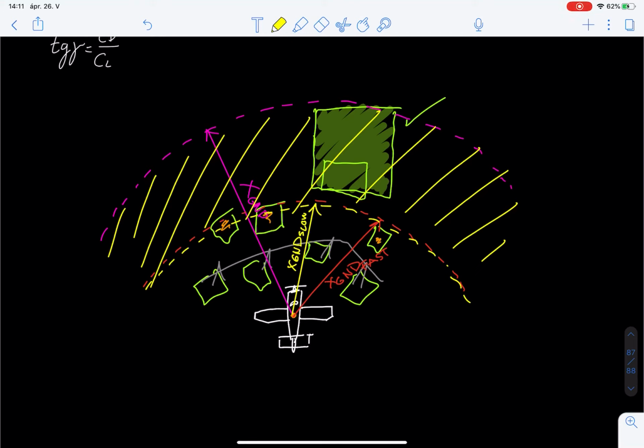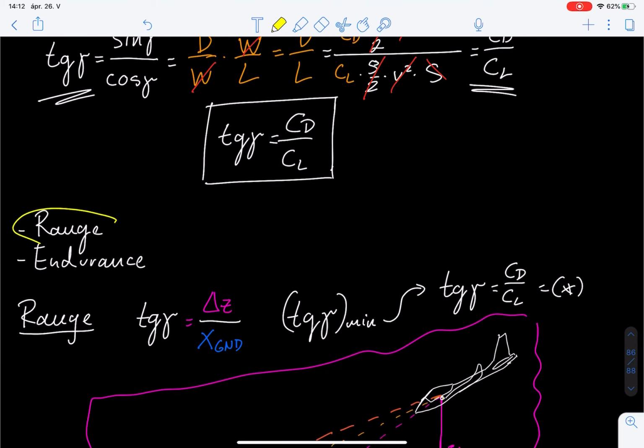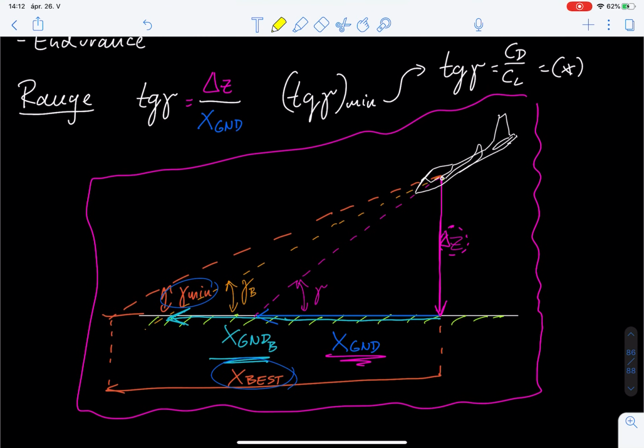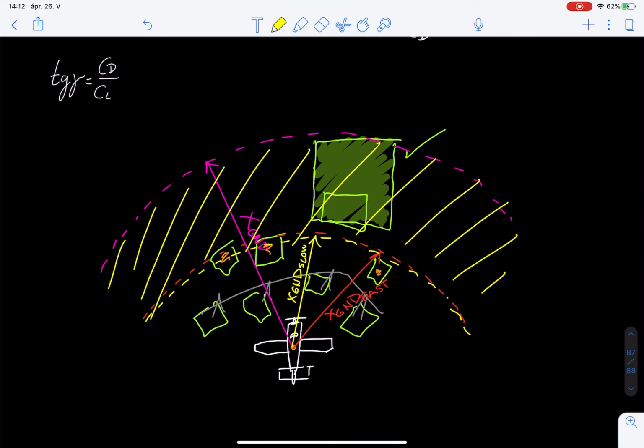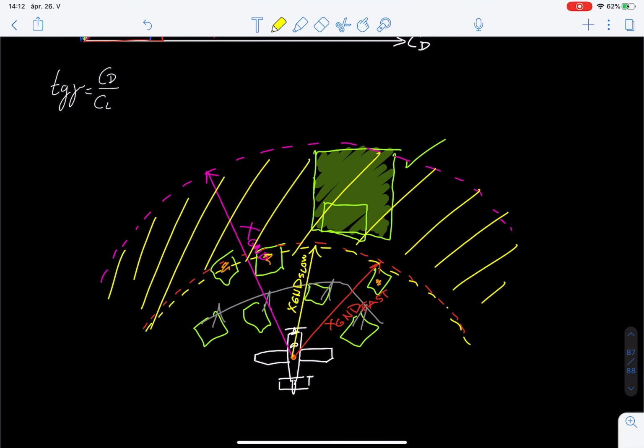But especially with a powered airplane which has lost its engine, you always want to fly with the best glide speed, because you're always looking to optimize range, because range is giving you options. And that's what you want the most. You want to have more options to choose your landing place, and maybe even, if the situation occurs, you can even reach the runway, right?